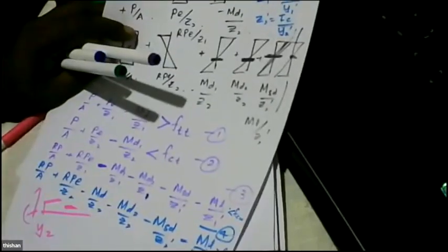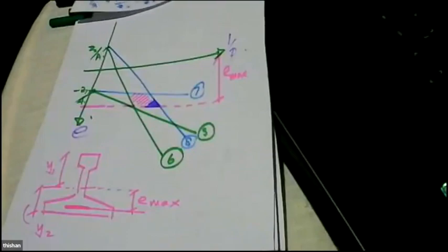So basically, the structure cannot deform on its own, and because of that, we are going to get a live load which is relatively low, because the load is distributed everywhere and all the beams are now carrying the live load. So you get an efficient section, a strong bridge, and above all, the most important thing is all these equations can be easily represented on a Magnel diagram.